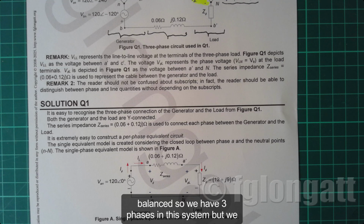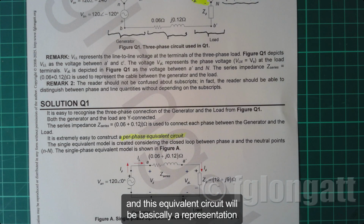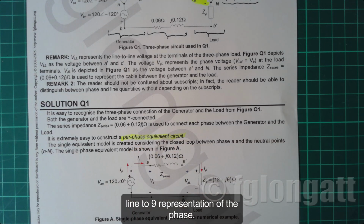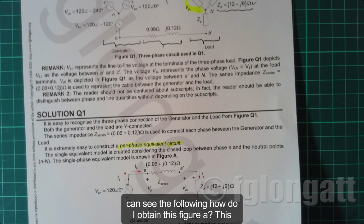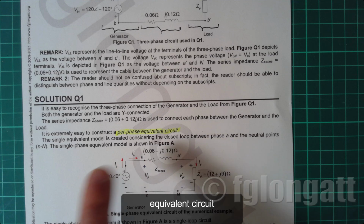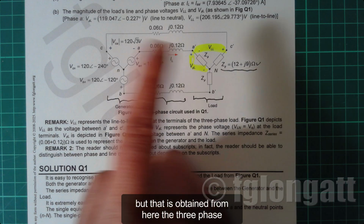So we have three phases in this system, but we can take advantage of the three-phase properties. We can create an equivalent circuit, and this equivalent circuit will be basically a line-to-neutral representation of phase A. Let me go back here a bit so you can see the following. How do I obtain this figure A? This figure A here below is basically the single-phase equivalent circuit, obtained from the three-phase circuit.